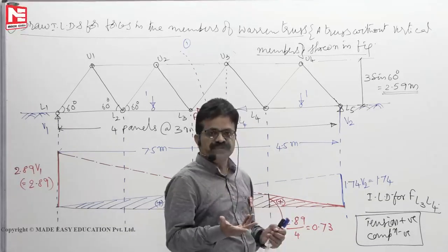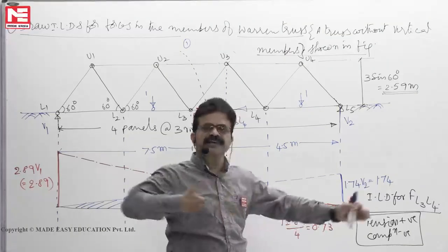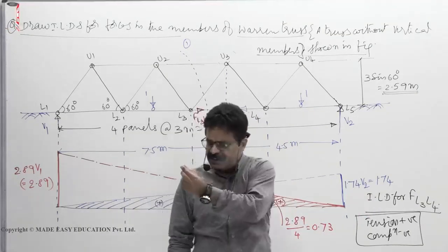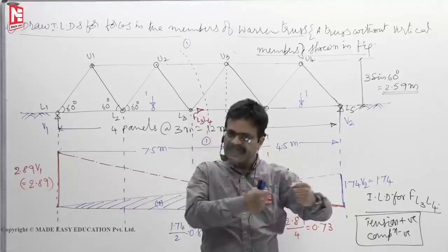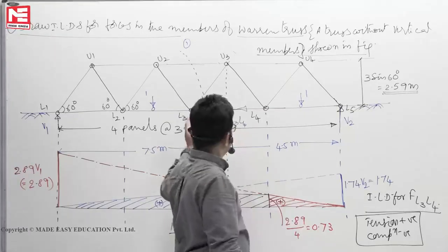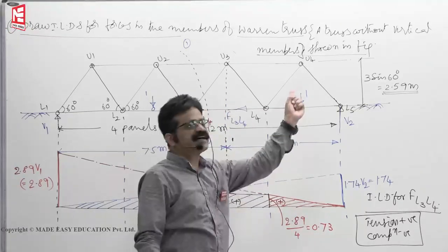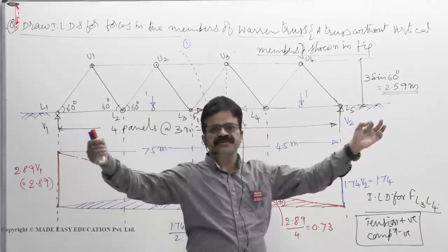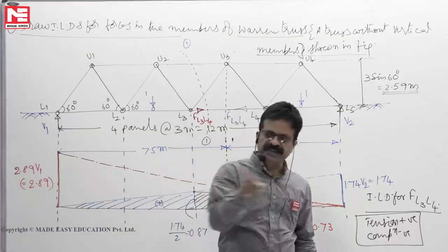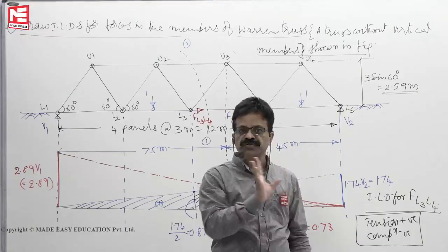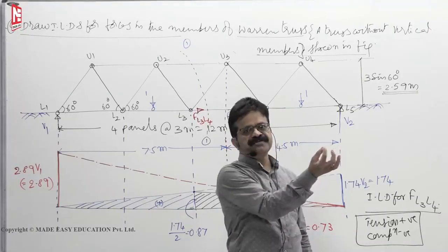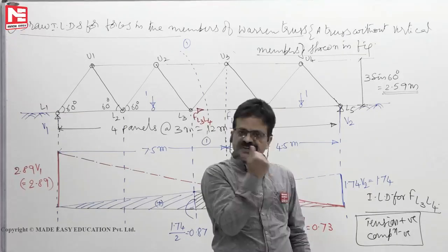So why do we go for 400? Why limit it to 400? Why can't it be 1000? Supposing the slenderness ratio is 1000, then it becomes so thin. It can take load, but the cross section will be so small that due to self weight itself, it will sag, like a cable. In a truss, even tension members should not lose their straight configuration.